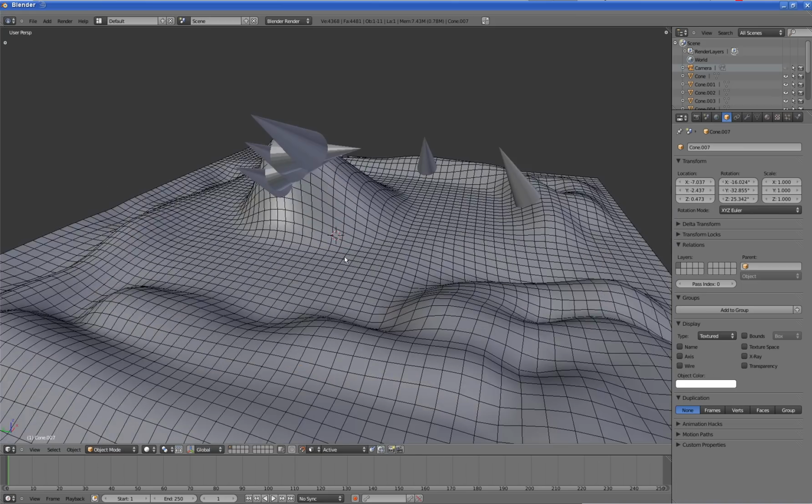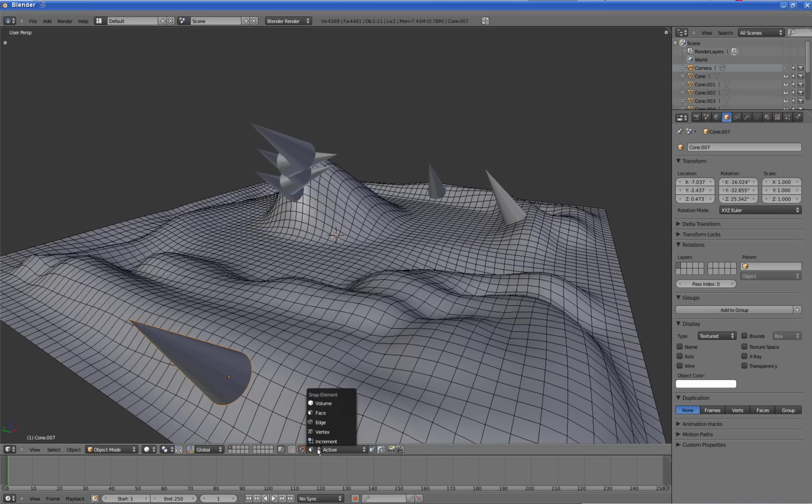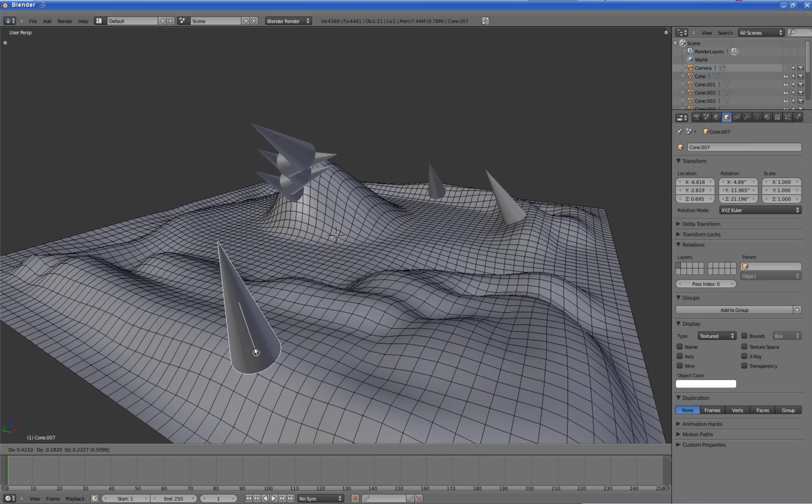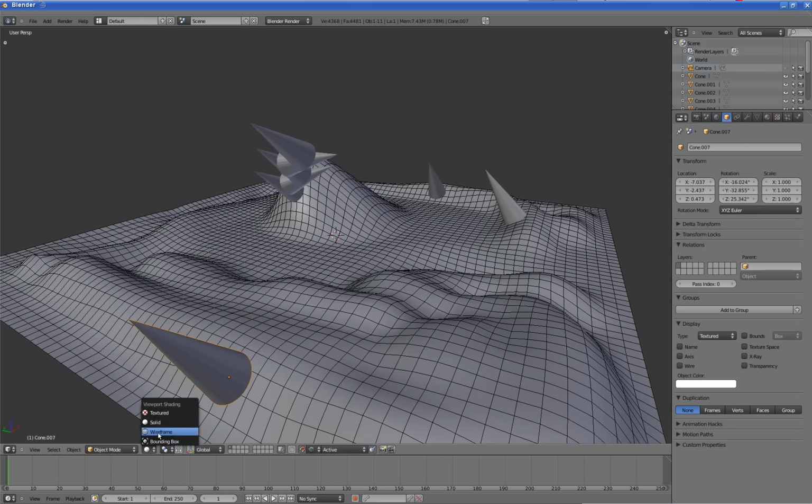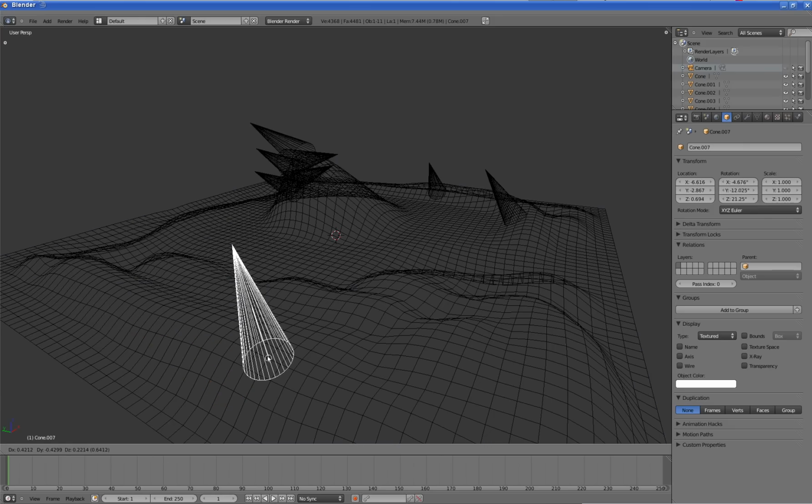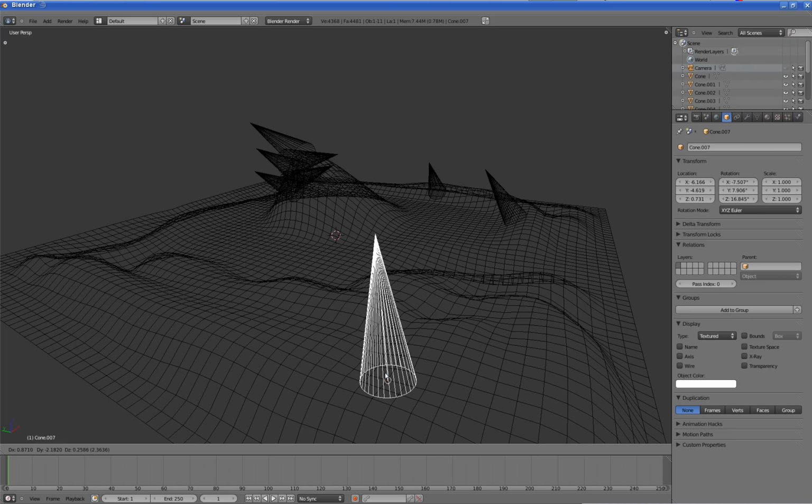Right, and if you want to place the object on a specific edge, you can go into edge select mode. Then select the object, and you'll see that now the movement is constrained to an edge. If you go into the wireframe mode, you'll see that the movement happens on an edge. So there you go, on an edge of the selected mesh. Just practice this stuff.